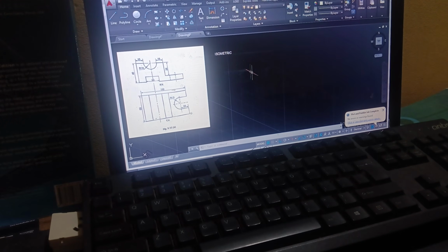Now first we have to draw the box of maximum dimension in the front view, top view and side view. Refer to the given two views, the front view and the top view. The front view length is 110 mm, the front view height is 40 mm, and the top view width is 60 mm. Okay, so draw the reference box in some contrast color.